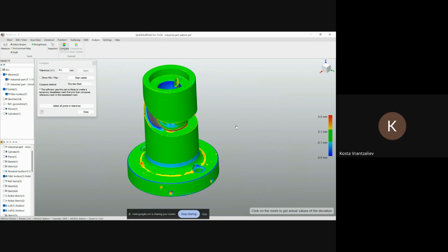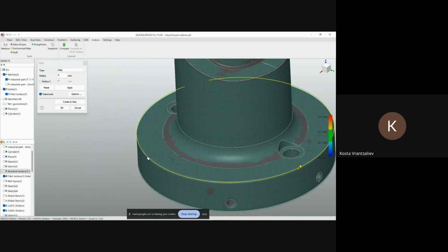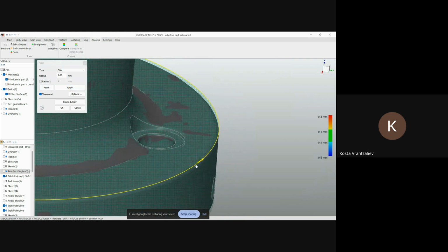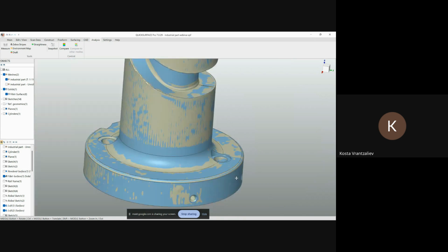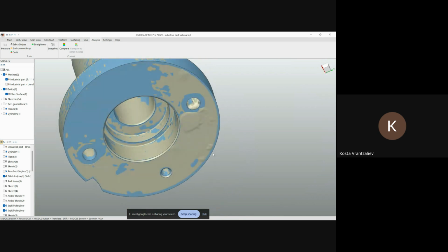The thing is that mechanical engineers need to have control, and the reason for reconstructing one by one is to have this parametric feature tree, because this is what you actually need at the end. That's why here you have this fillet. You can come back later and tweak and change it to 2.7 or whatever. So this is what the design intent is.